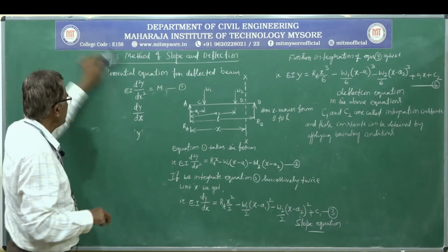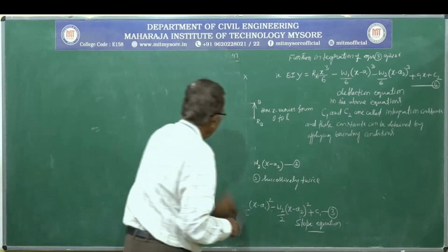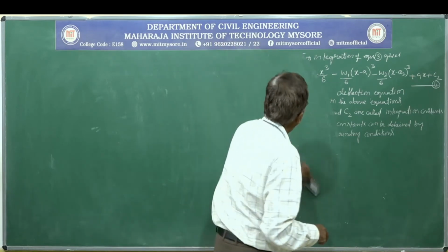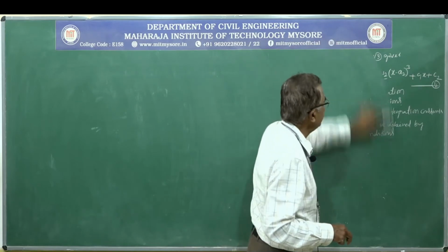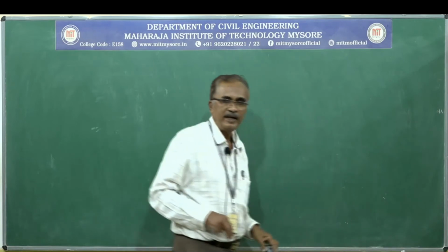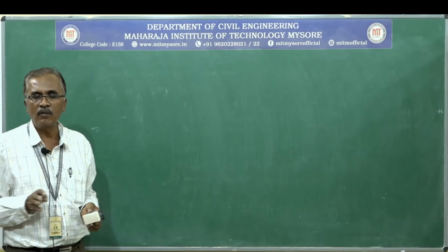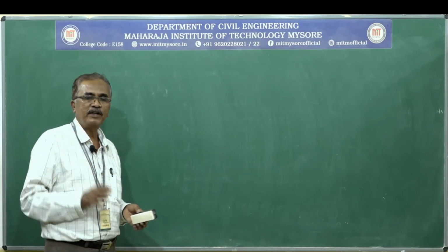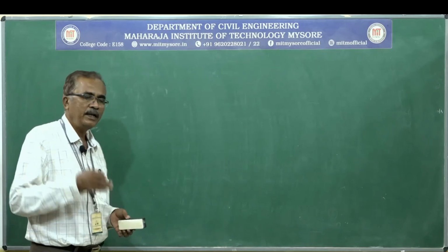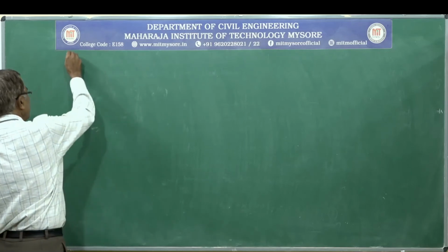Regarding boundary conditions, let us discuss in detail. Once we know the boundary conditions, along with this Macaulay's method, knowing the differential equation for the deflected beam, we can easily solve any type of numerical problem to find slope and deflection at any given point of the beam or for any combination of loadings. Now, boundary conditions.